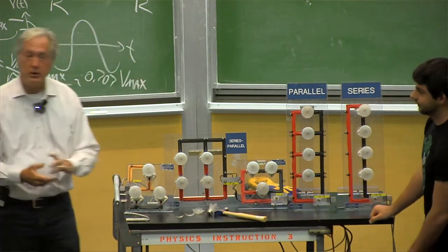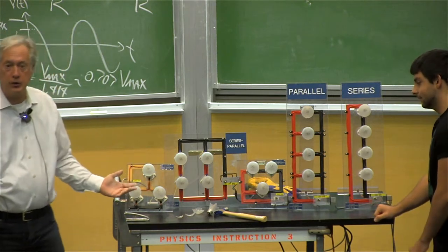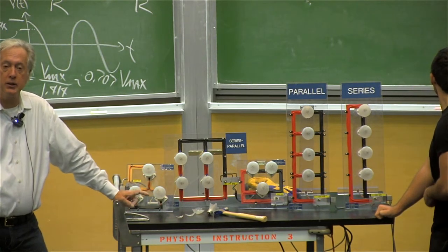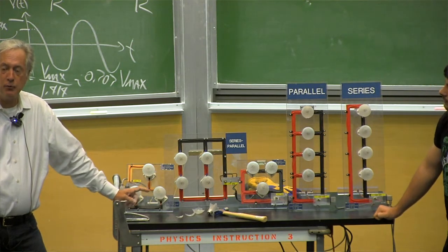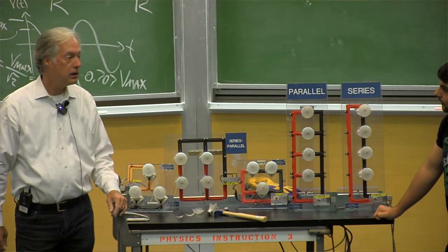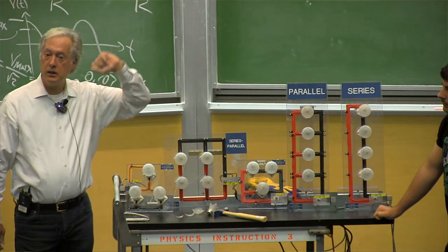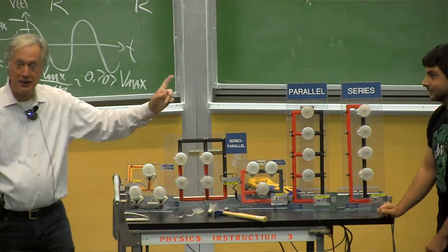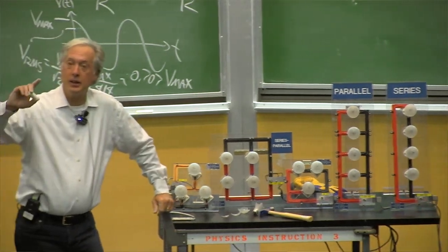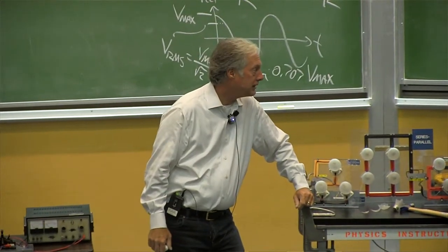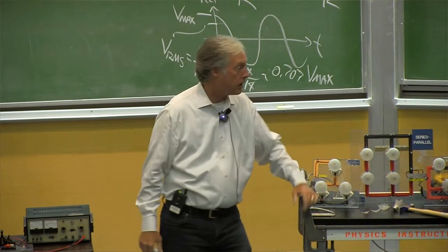So you should be able to say what is the resistance of this light bulb from the power dissipation. And from the power, what's the power when the thing is on? 60 watts. Say that louder. 60 watts. Excellent, Sam. So 60 watts, and what's the voltage? 120. 120 RMS, right?